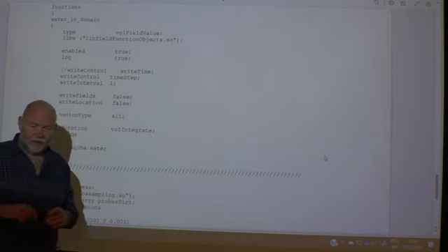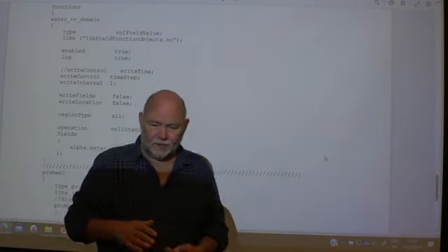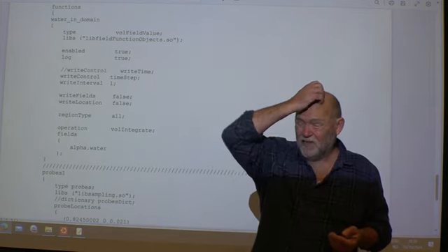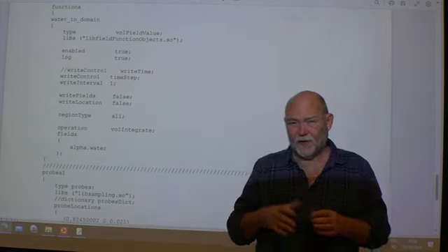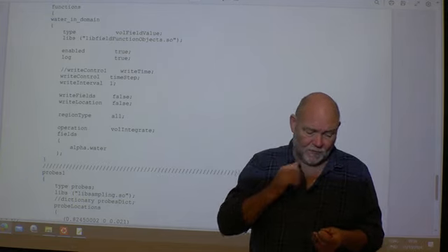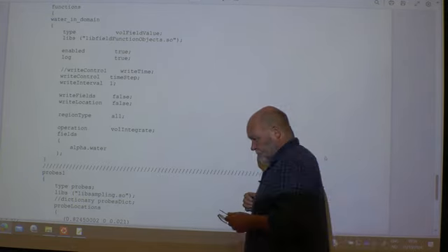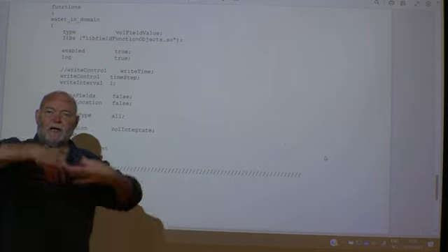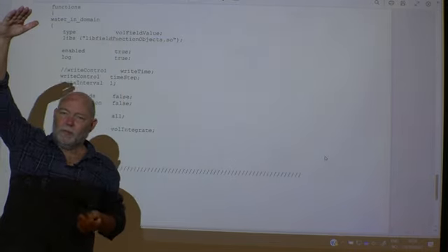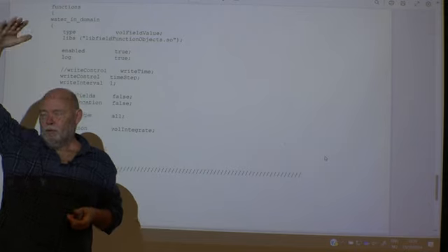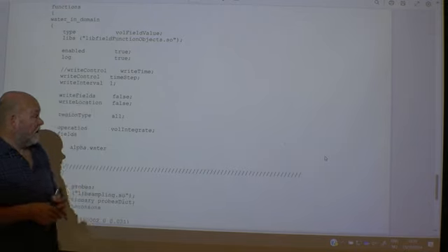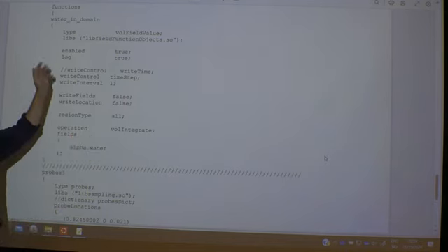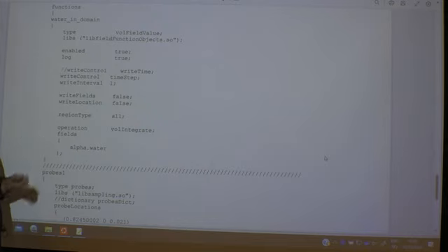It should be constant, at least initially, but remember you have an open top boundary condition, which is like the same we had in the 2D block mesh, no, the dam break case. When the water is sloshing and then splashing upwards and goes through the top, it's going to disappear. What comes back is going to be air. Hence, this volume is not going to be constant all the time. But initially, of course, all the water should be the same.